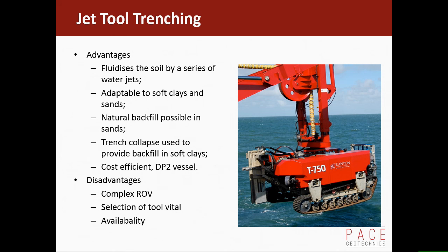Soft clays, it's good because the soft clay is fairly easy to jet, but you don't get any backfill unless you do a trench collapse pass. And from a cost point of view, you don't need a particularly big vessel, just a fairly cost efficient, relatively small DP2 vessel. Of the disadvantages, the most important one is selecting a big enough trencher for the material you've got. Using an underpowered trencher is just a hiding to nothing.